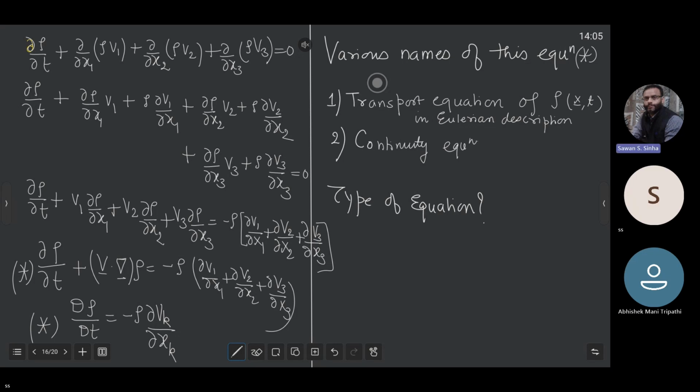So this is what I derived towards the end of the previous class using RTT differential form. Then I am applying the product rule of differentiation for these individual terms here. So these three terms give me 6 terms. I take this one, and this one, and I keep them on the left hand side. The other new 3 terms I push on the right hand side.